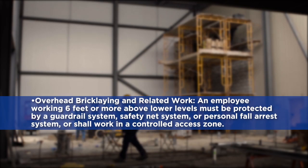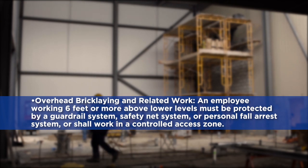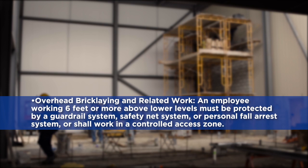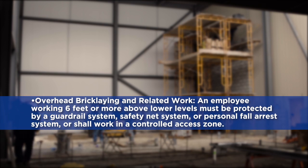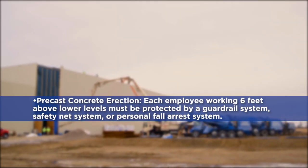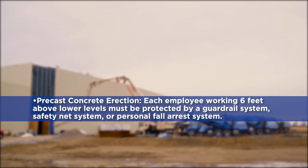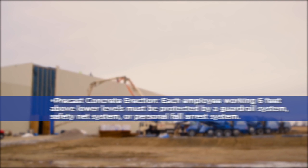Overhead bricklaying and related work. An employee working 6 feet or more above lower levels must be protected by a guardrail system, safety net system, or personal fall arrest system, or shall work in a controlled access zone. Precast concrete erection. Each employee working 6 feet above lower levels must be protected by a guardrail system, safety net system, or personal fall arrest system.